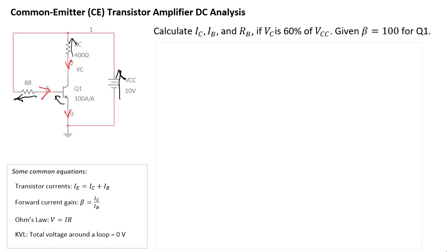All right, let's talk about VCE. That's VCE here, so VCE is obviously going to be in this direction. And to complete our VCB part, the collector is going to be, because this is NPN, it needs to be reverse biased. Remember that? It needs to be reverse biased for amplifier operation mode, or forward active mode, for the NPN transistor. So VCB is going to be in this direction, so that's VC positive in that direction.